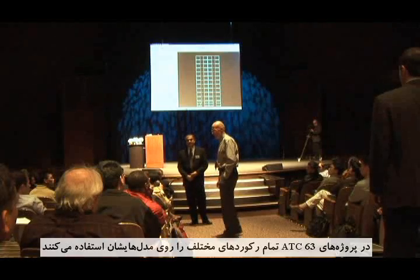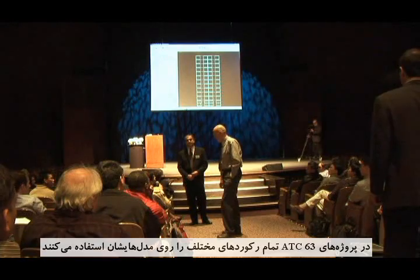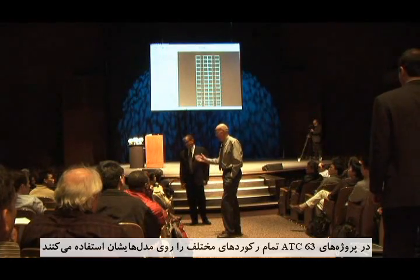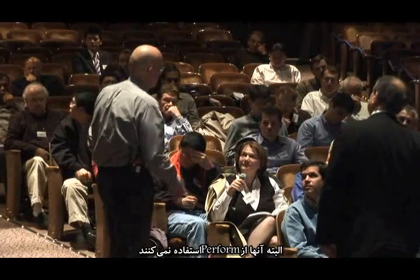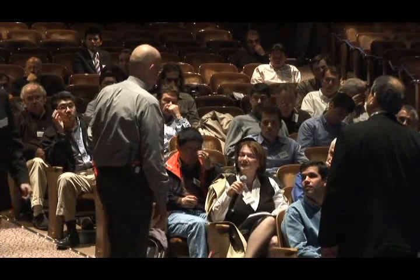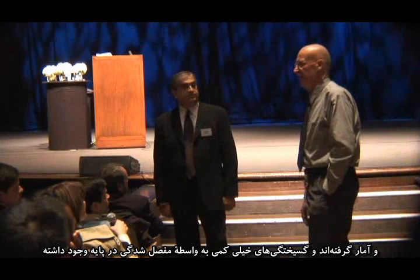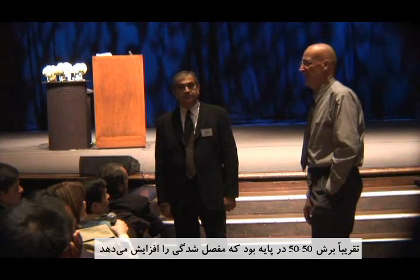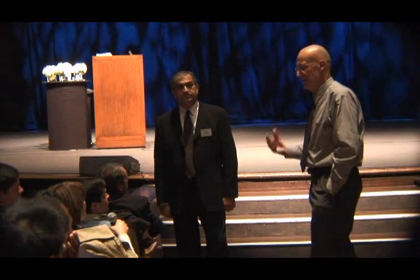You know, I don't know. I just picked one. The ATC 63 project ran a whole slew of different records, and on their model they didn't use Perform. They used OpenSees, but they observed the same thing. You know, they did statistics, and very few failed by hinging at the base. It was roughly 50-50 shear at the base or hinging higher up.